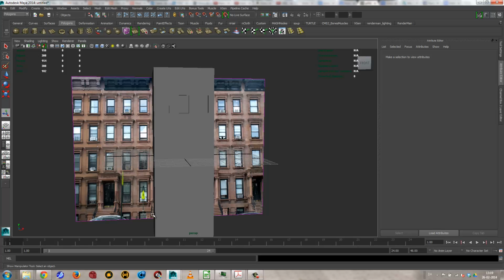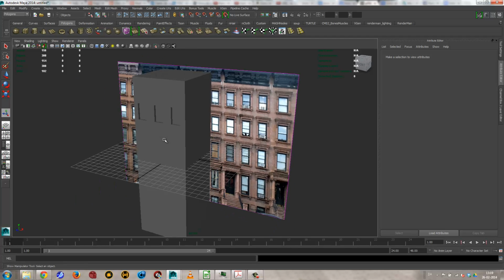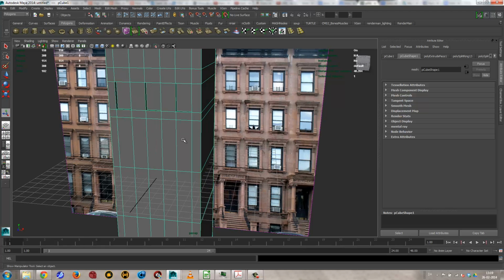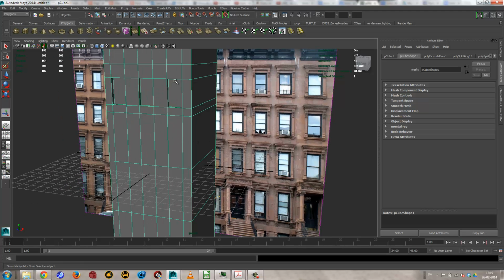So these are both ways to do it. It depends on how you want the model to be, if you want it to be a solid model or you want it to be a segmented model. So the nice thing about this is that you get decent lines running through the whole model. You could also use booleans to cut it in, but I think this will work better because you get a nicely tessellated model. You get the nice segments all the way.